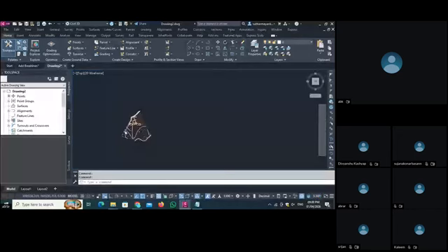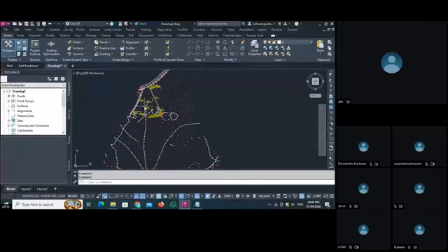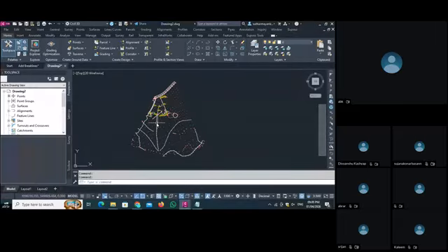My motto is that whenever you already have one point file and you have to import another file, this type of problem happens if the point format is not good, or you mismatch anything, or because in this file format we did not set our units.